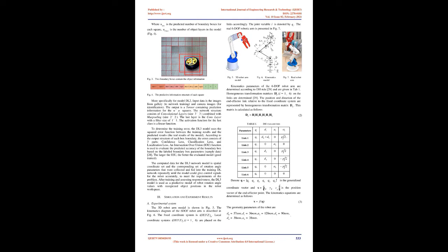The robotic arm receives voice commands from the operator using the voice recognition module that converts human voice containing control information to text in the program. The robot control information contained in the voice includes the direction of movement of the robot, turn to the left or the right, what action the robot needs to perform, the action of grabbing or dropping, identifying the object (wheels, trays, boxes), and distinguishing features of objects: color, shape, size. The input voice and the output control signal must be defined to solve the robot control target.